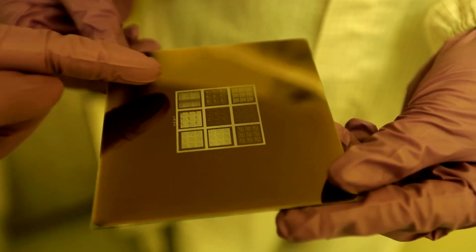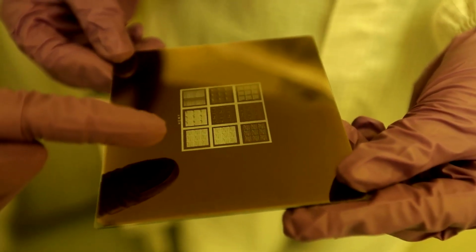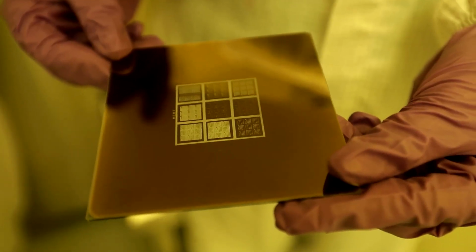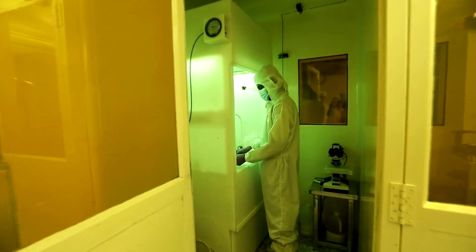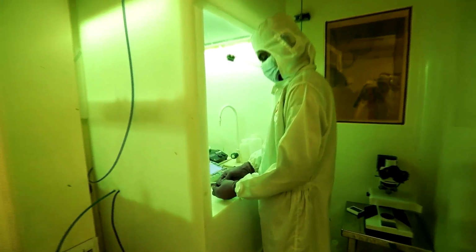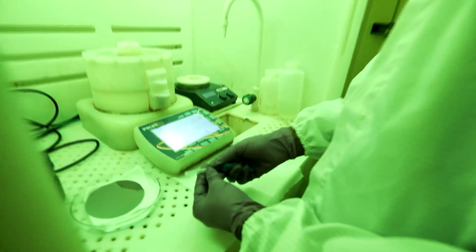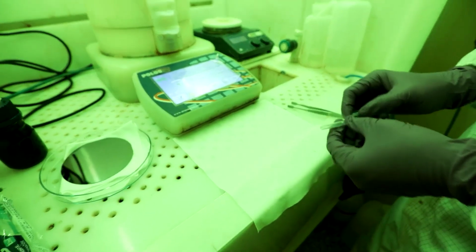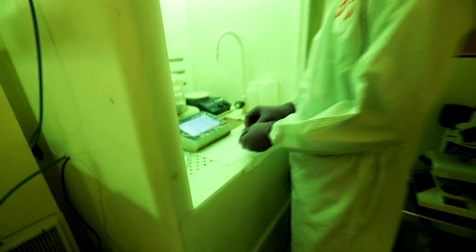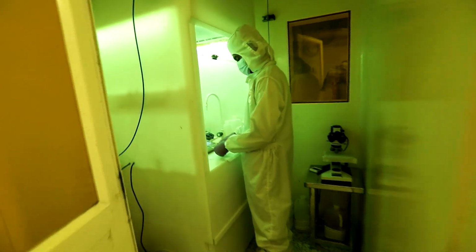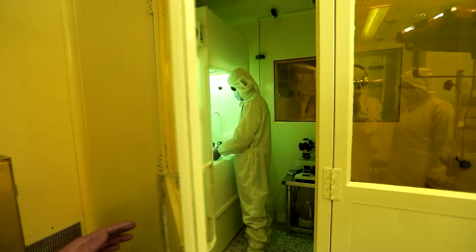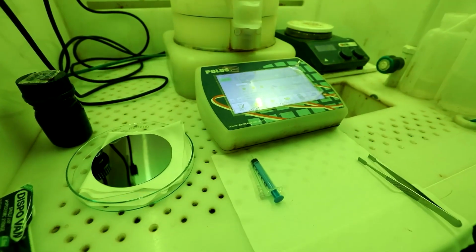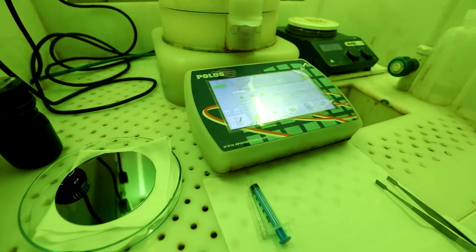So now we are going to transfer these patterns, shown on the mask plate, onto this silicon dioxide substrate. There are three basic process steps to transfer a pattern from a mask to a wafer, that is, spin coating of photoresist, exposure and development. Let us start with a spin coating procedure. Spin coating is the procedure for making very thin films of photoresist onto the substrate.